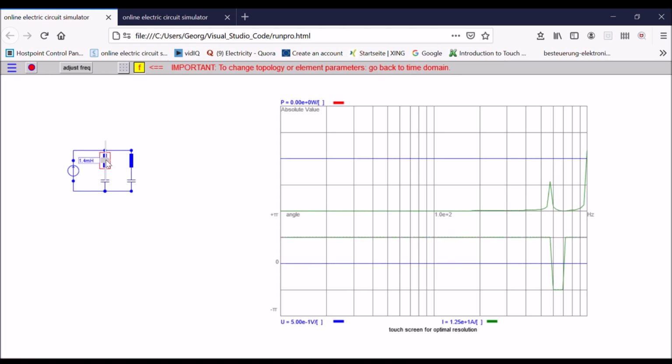takes care of the 250 Hertz, so that reactor has to be tuned accordingly. Just below 250 Hertz, that's what it is more or less. And the second one, I take it to close to 350, a little bit below. So this is what I have now. That should be a little bit below the frequency I want to remove. So the second reactor would now have a value of around about 4 millihenry.